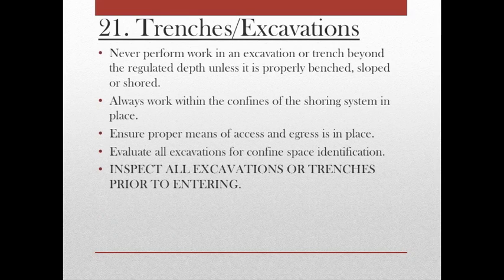Trenches and excavation. Excavations and trenches have additional hazards that require special precautions prior to entering. Supervisors shall be competent in the identification of hazards and determination of protective systems as required by Cal OSHA. Never work in an excavation or trench beyond the regulated depth unless it is properly benched, sloped, or shored. Always work within the confines of the shoring systems in place. Ensure proper means of access and egress is in place. Evaluate all excavations for confined space identification. Inspect all excavations or trenches prior to entering.